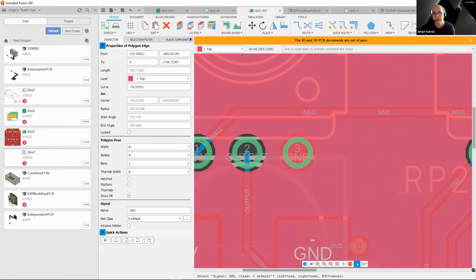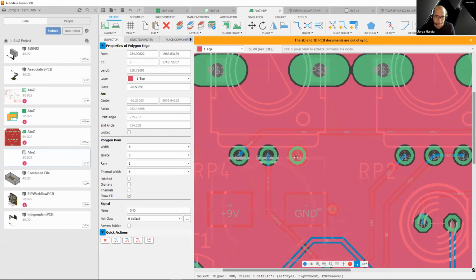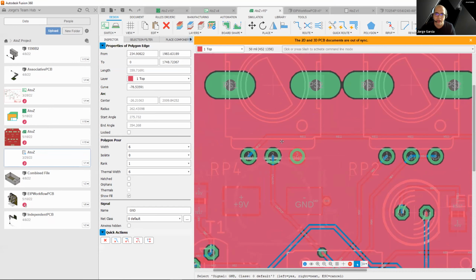Now, when you do this, you have to make sure that your manufacturer can adjust their process for this, because you're going to need to get the board hotter in order for that part to solder onto it. And it requires a lot more finesse, because the longer the board is hot, the more risk there is of actually delaminating the board itself. So there's a Goldilocks zone on the manufacturing side that your manufacturer has to be comfortable dealing with when you do this type of thing. But it's very common. There's a lot of components that need that.